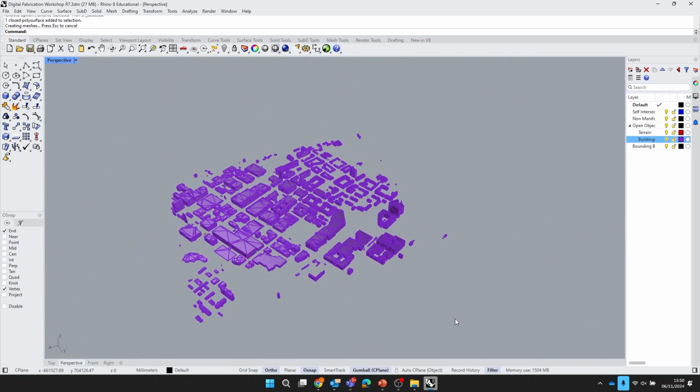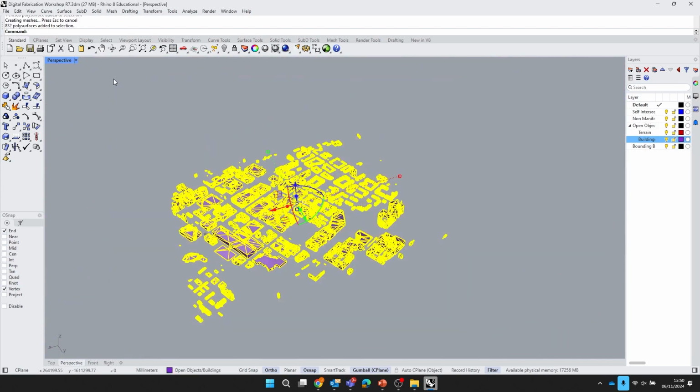And you can select all of those and do merge all coplanar faces for all of them. You don't have to do them one by one. That's just going to run through and do all of those. Oh, also for Make 2D, when you're doing diagrams of big site models, clean them up like this first, just to get them as clean outlines rather than triangulated. Make 2D, and you get perfect diagrams of all the building outlines. It's another cool thing you can do with it.